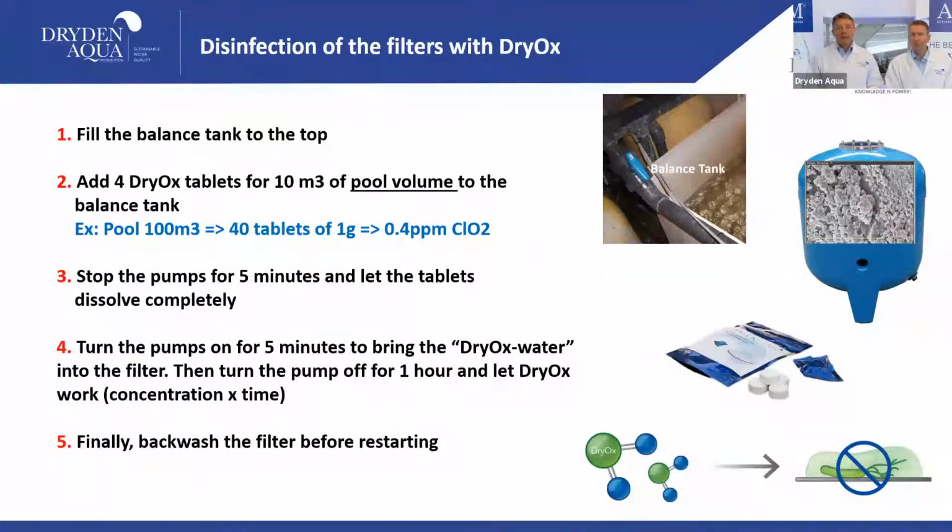Now, as I said, 90% of the problems really come from the filter media that you see here. If you have a contaminated filter media, I'm not talking about AFM usually. If you have a problem with AFM, it is only because your backwash is nonexistent. The moment you have a nearly reasonable backwash, you will not have this problem. But you can definitely have this with sand, especially if your backwash is not good. So what do you do? Okay, let's go through the steps.